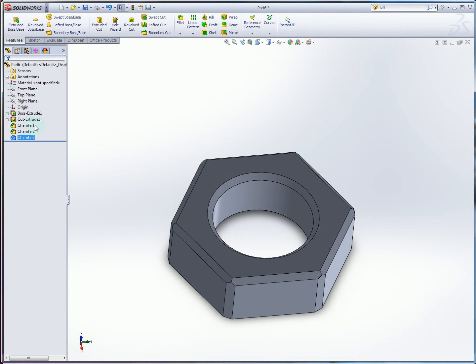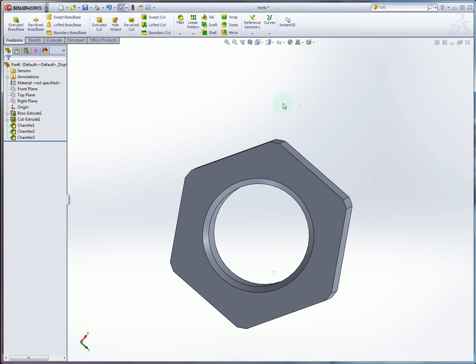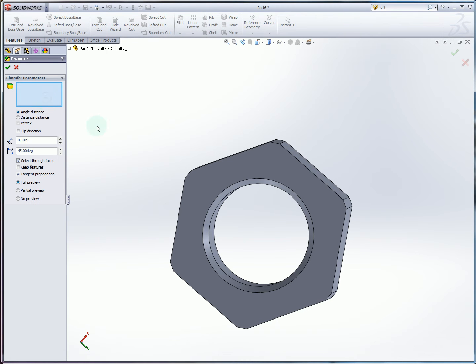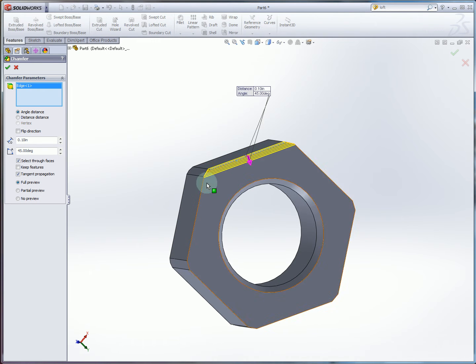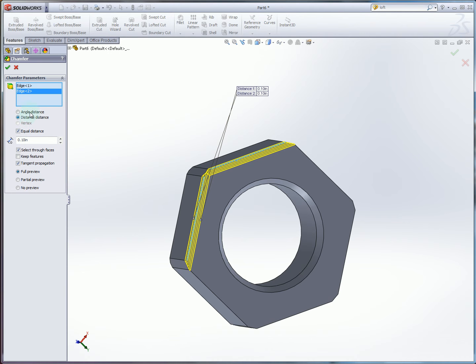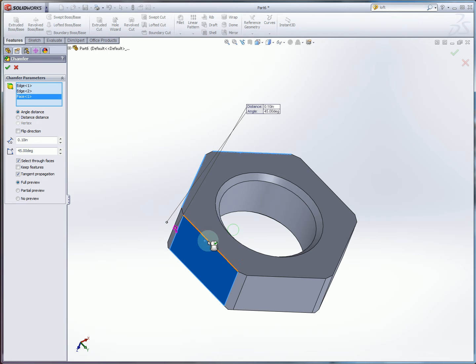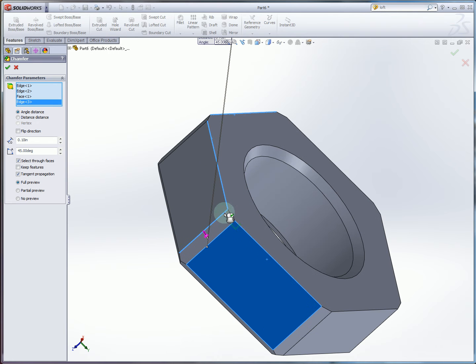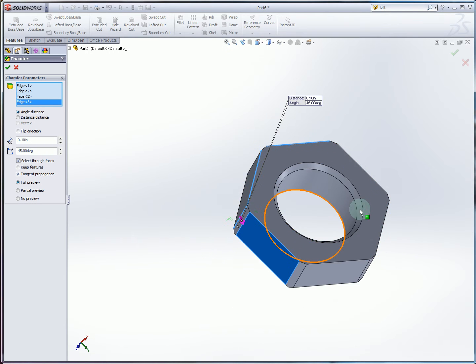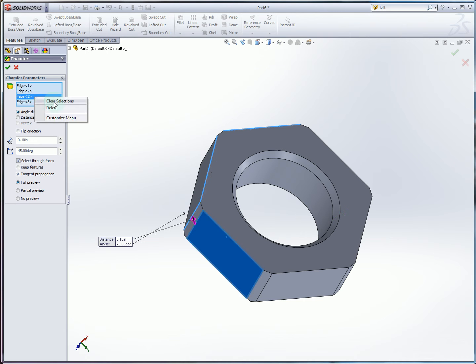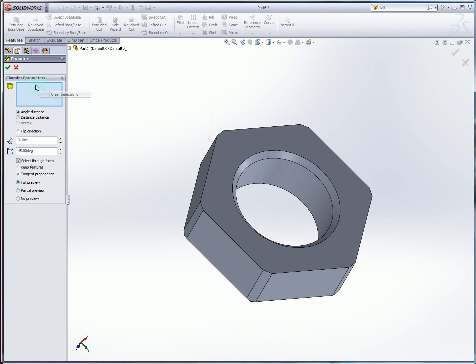So to quickly review, when you're creating a chamfer, it's going to be under fillet. You basically just have to specify the edges that you want to chamfer. You want to choose a method to do the chamfering, be it angle and distance or distance and distance. And that's pretty much it. Just make sure that you specify chamfers in a reasonable sequence. Try and avoid chamfering chamfers just because at some point it will break the solver. And that's basically it.